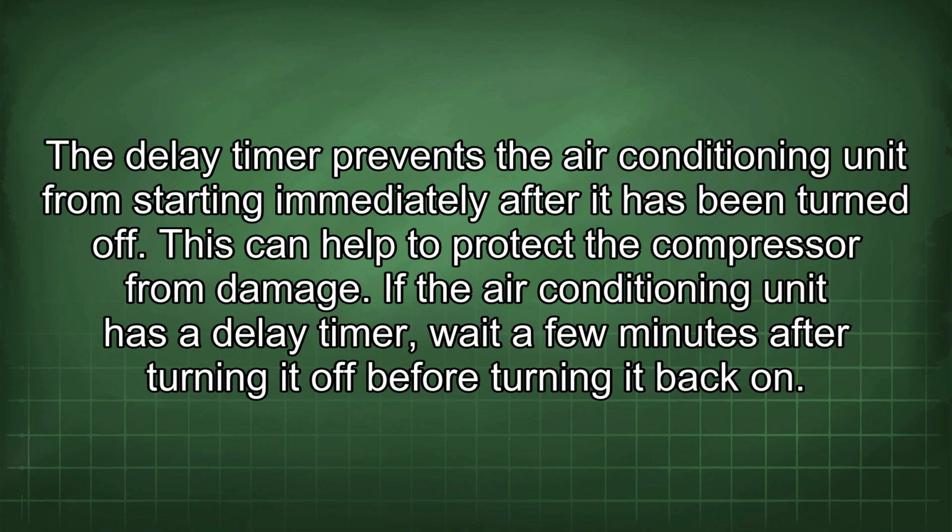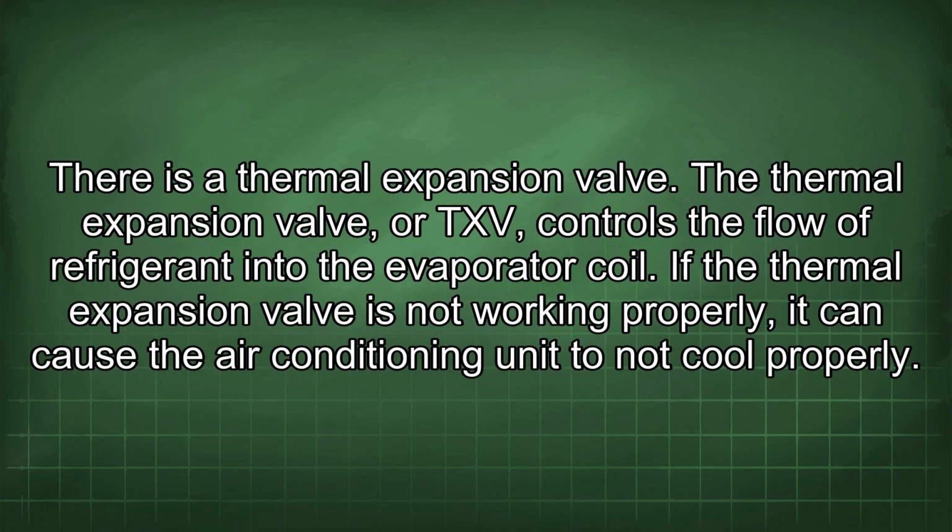The delay timer prevents the air conditioning unit from starting immediately after it has been turned off. This can help to protect the compressor from damage. If the air conditioning unit has a delay timer, wait a few minutes after turning it off before turning it back on. There is a thermal expansion valve.